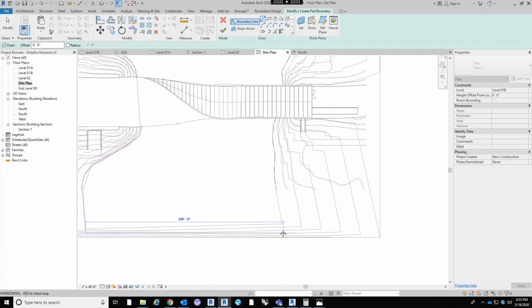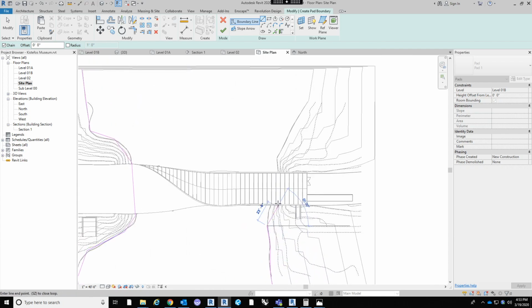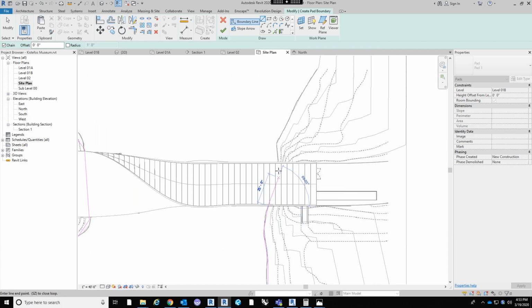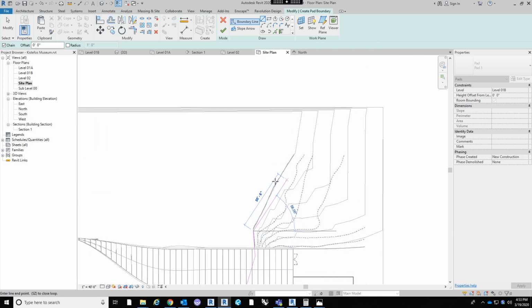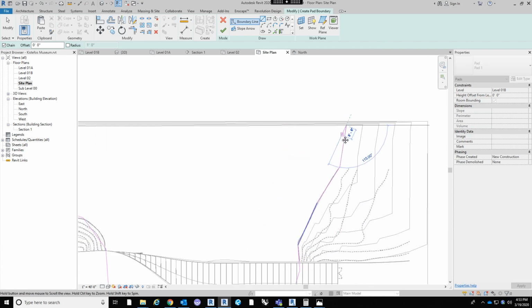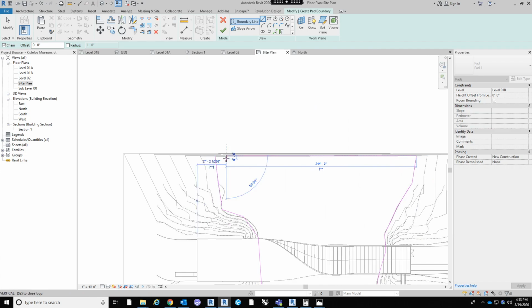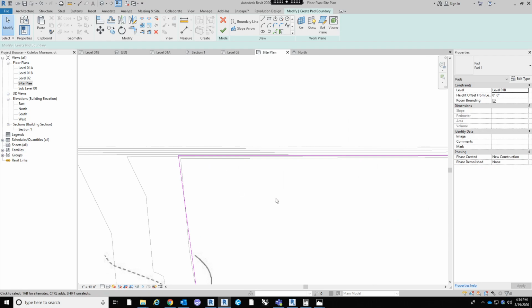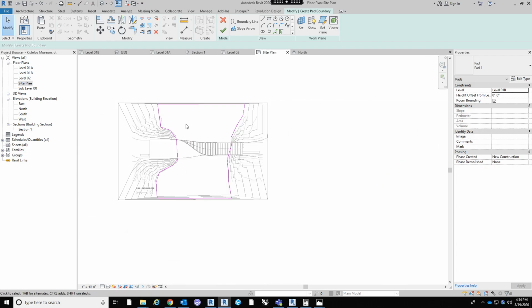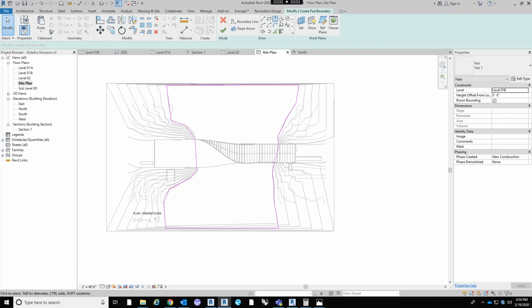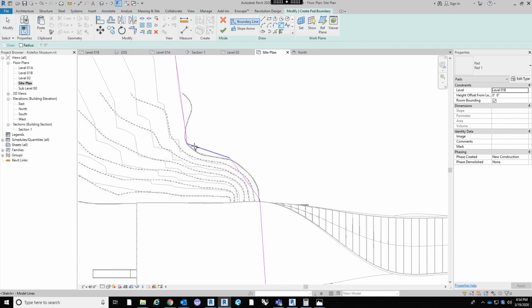One thing to remember with a building pad and a split region is you cannot go outside of the surface. You have to stay inside. So that's why I always go outside of where I need the specific topography changes to be, because I'll have these weird outside unresolved edges. Alright, so I got that. I'll go back into my fillet arc and round some of these out.